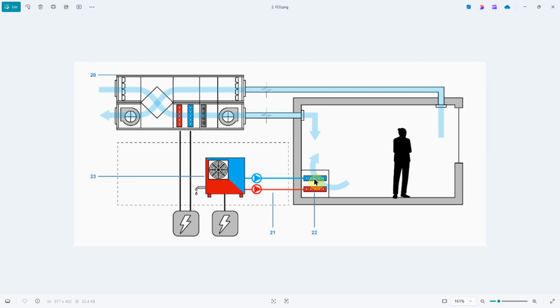And these are the coils. They're coils because they have a lot of surface area, so that the air blowing across them has a lot of access to that temperature that's in the water. So we're heating and cooling with hot or cold water from the heat pump, blowing air across it to heat and cool the room. The only thing we're using this unit for now is to bring in fresh air, and fresh air is a lot less volume. We're just talking about this person surviving, so we can have much smaller ducts.